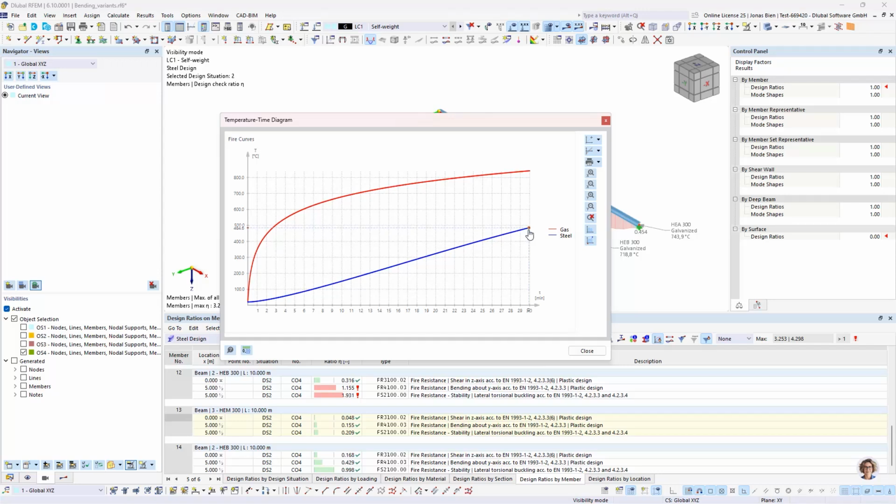And that's mostly because for the whole 30 minutes, we are below a member temperature of 500 degrees Celsius, which means that until the end we can leverage the lower emissivity of the member surface. And then, of course, the benefit is much greater, because it's more or less the integral of the heating over the time.